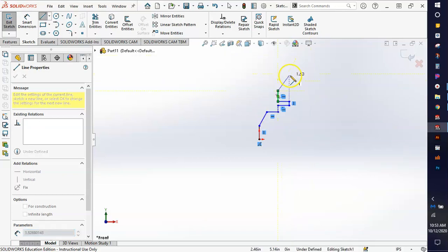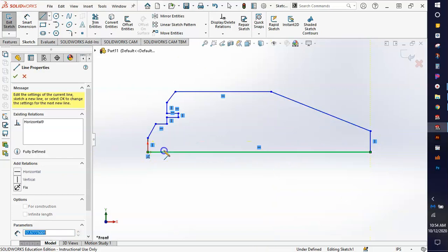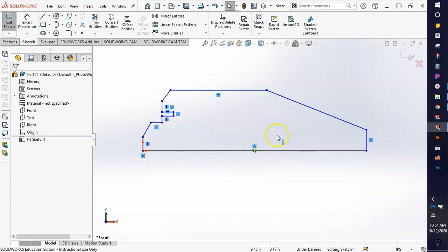straight up, another angle, and make sure that you're not set to parallel here because we don't know if it actually is or not. Then across the top, back down on another angle. Again, let's not be perpendicular. Don't have anything that's preset because we don't know if it's actually perpendicular. Try to just draw an angled line. And that's going to come way down here. Then straight down. And I'm going to try to make sure it's across from my origin and all the way back over. Okay, so I'll hit escape. This bottom line, if you just set that to horizontal, it might fix up a bunch of your issues here.